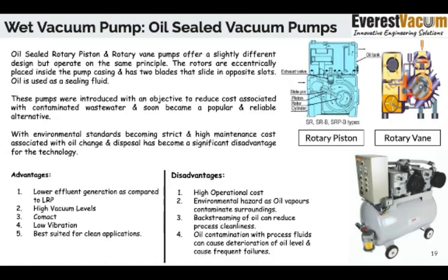The advantages that these type of pumps offer: number one, lower effluent generation as compared to liquid ring pumps. Number two, high vacuum levels. Number three, they are compact. Vibration levels are low, and they are best suited for clean applications. The disadvantages that are there in such cases: A, operational cost is very high.